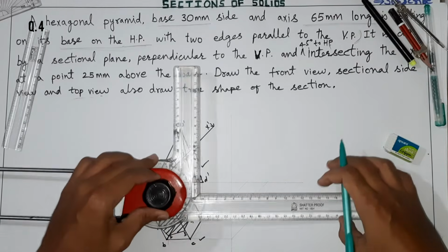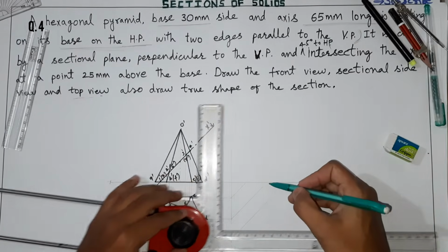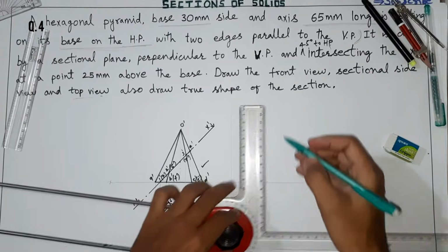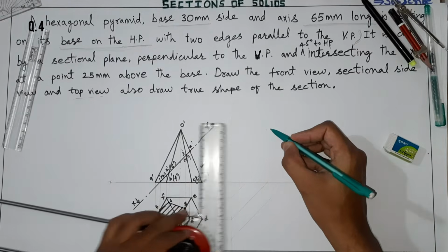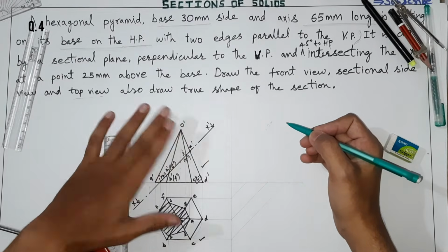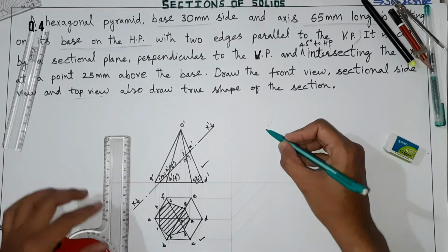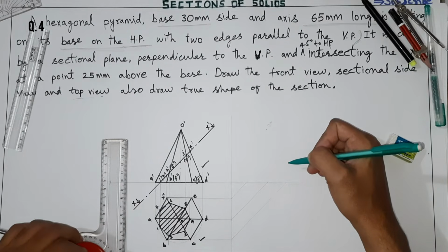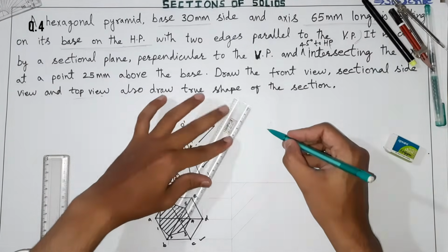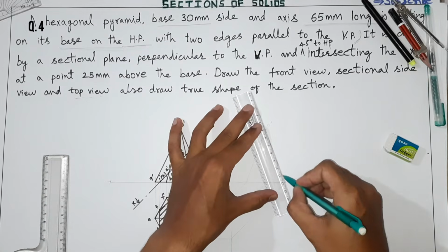Then what you need to do is align this properly and take the center line up to here. Just draw a thin line or just point apex O double dash in the side view. Anyhow we will remove it after cutting, this upper surface will be removed. This is just for reference. Why? Because we have to construct the slant edges, the rest of the slant edges. Now see, I will join this with this scale. So this is the side view completed.